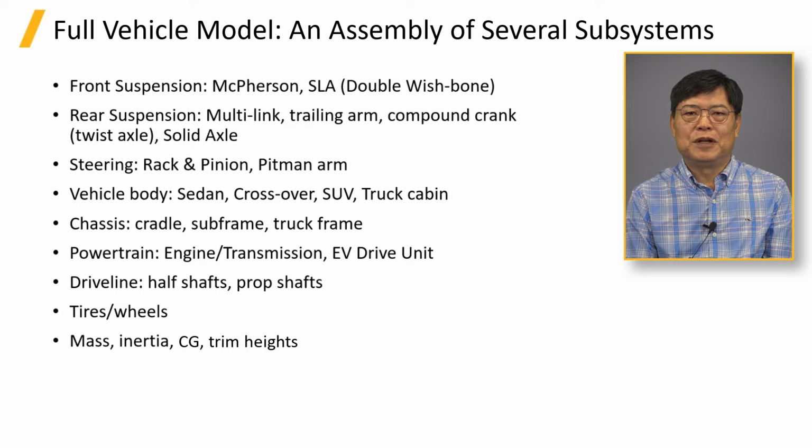They should be included to answer driveline-related questions about half shaft vibrations and power hop. Simple tires could be replaced with the high-fidelity commercial tires for nonlinear handling, rough road simulation, and rim ground-out conditions. The vehicle mass, inertia, center of gravity, and trim heights also affect the vehicle performances substantially in some cases, thus should be carefully modeled. A takeaway from this slide is that the fidelity of a full vehicle model is associated with the questions asked for virtual simulations.